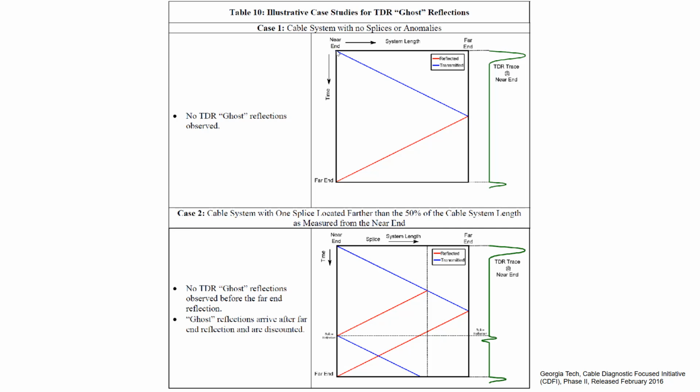So when we send a signal from here, it travels on the transmission line, the cable. This is the physical position at different instants of time. So this is the transmitted signal. Since there is nothing in between, the transmitted signal travels smoothly and reaches the far end, and there it gets reflected. The reflected wave is given in red color. This is the reflected signal, which will travel again and reach the near end.